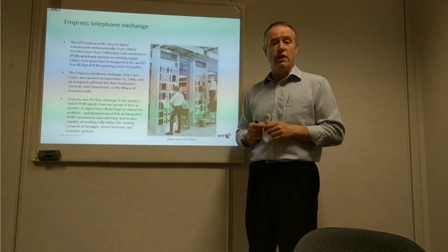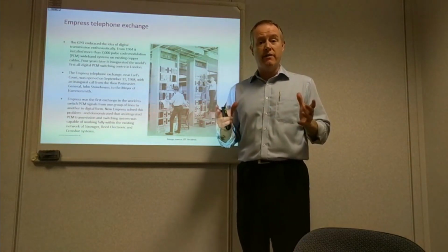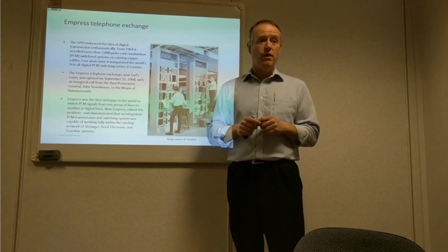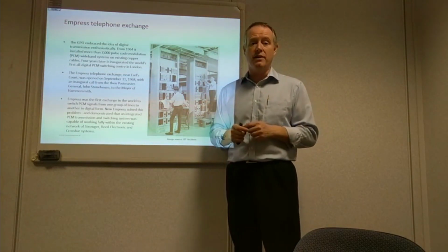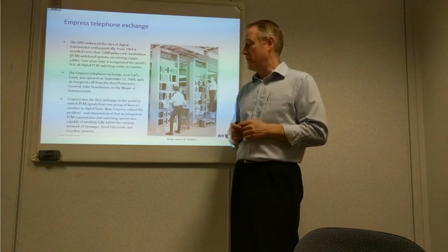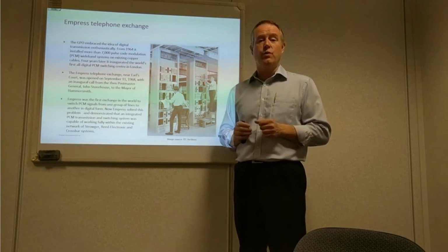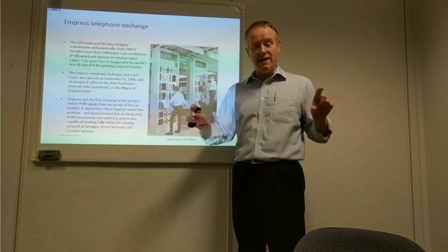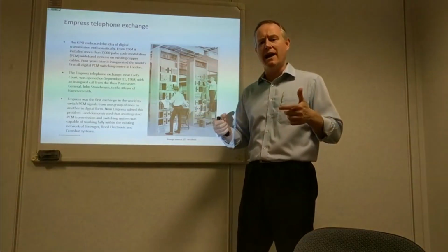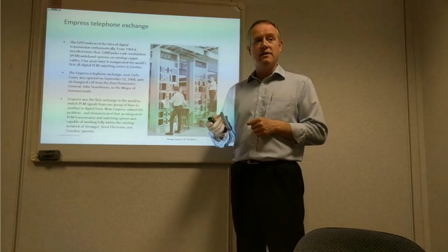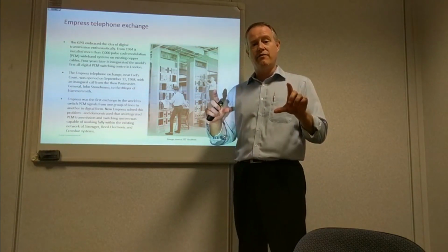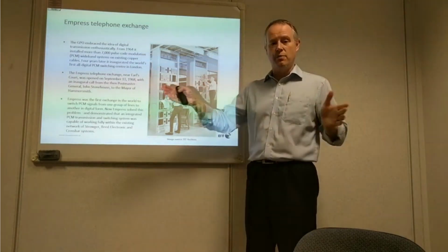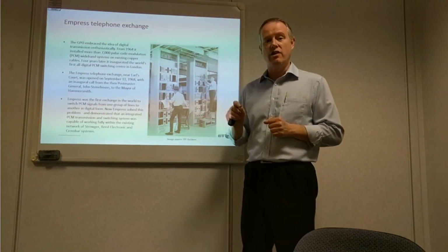And early digital switches often had a rubidium frequency reference on board. In fact, some of the very early ones actually had cesium rather than rubidium. So cesium tended to be deployed into the actual switch itself, so a very accurate, very expensive clock to guarantee that performance. But over time, again, developments in oscillators meant you didn't need to have a cesium reference on every switch, and in fact you could deploy a small number in your network and carry synchronization over the line.